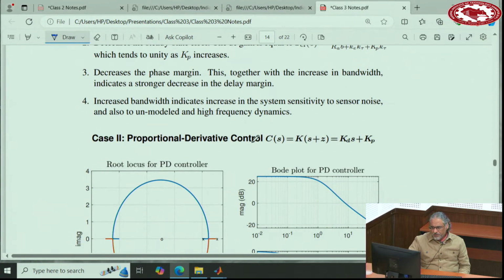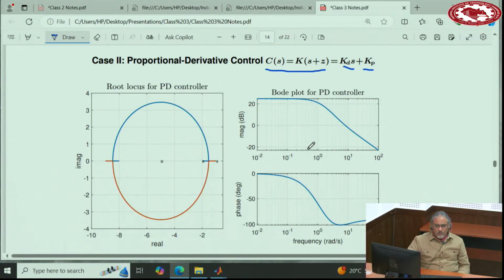So here's the explanation. The second type of controller, one level higher, is proportional derivative, which is called PD. Now we have one proportional and one differentiation. What it does, if the original poles are here in the root locus, is push them to the left. When you push the poles more and more to the left, you can make the time constants of the system smaller. The response becomes faster. So with this one, you can make the system significantly faster if you want.